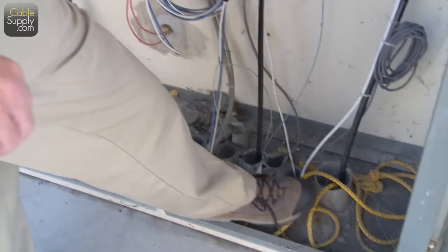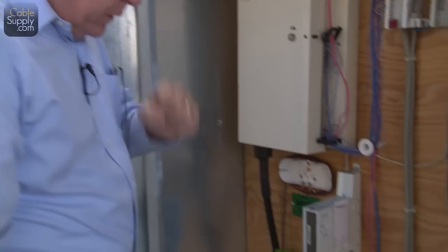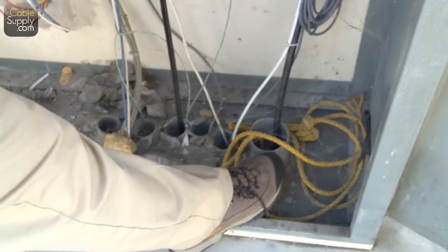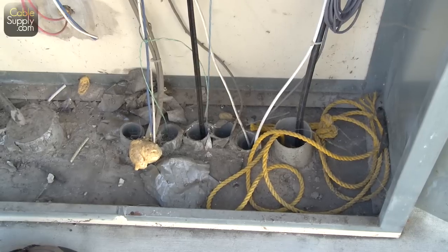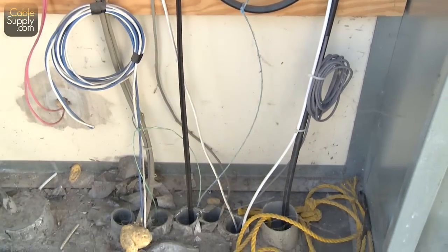A good thing here is this is a pull rope. So if someone else has to pull in more cable, the rope is right there. What they do is they pull in the cable, then as they pull in the cable, they attach the rope at the other end, rope and cable. So when they get the cable here, they have still another pull string here. We call it pull string, but in this case it's actually a serious rope. These big ones go out to the street. The smaller ones go into the building. You can see this goes into the building. This is attached to the other end, so if you need to pull more cable into the MPO, that's how you would do it. A special circuit.